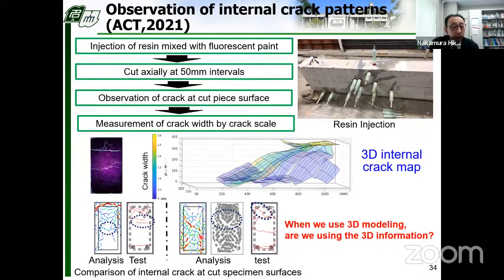This shows the crack pattern in cross-section obtained by analysis and test at different sections. The interesting finding is that a horizontal crack at mid-height in the area and an inclined crack propagating to the corner were observed. RBSM also simulates the behavior.